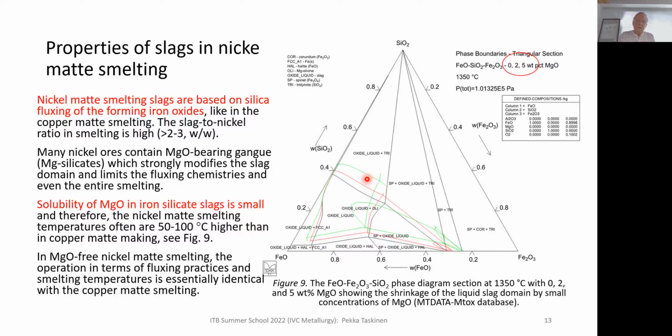So in some cases you may not be able to empty the furnace because the tapping periods are extended so much due to this high MgO in the slag that something must be done.